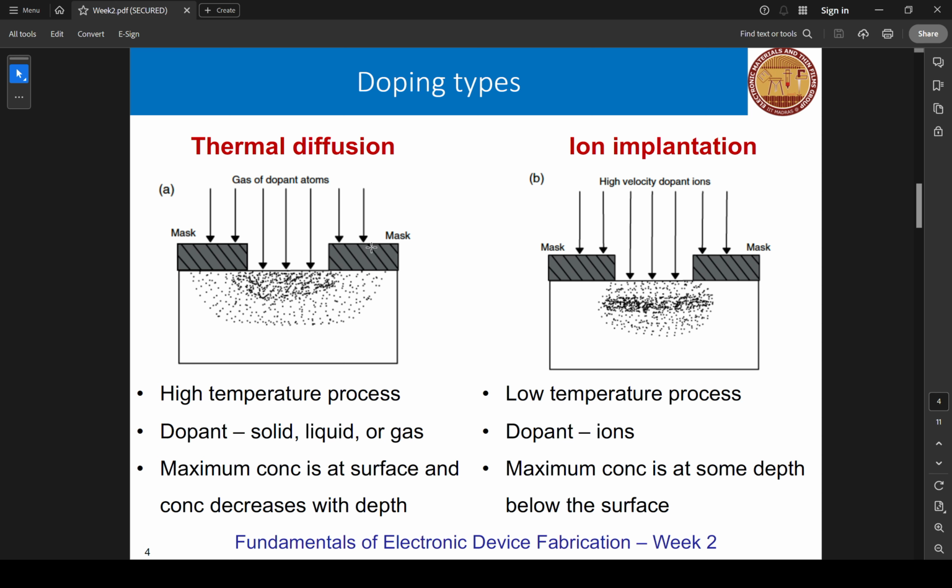So that will change due to your SiO2 blocking some amount. That is mainly dependent on your ion implantation method. So your SiO2 is blocking some. When the ions are entering into your wafer, they are losing energy as they travel through your wafer, right?